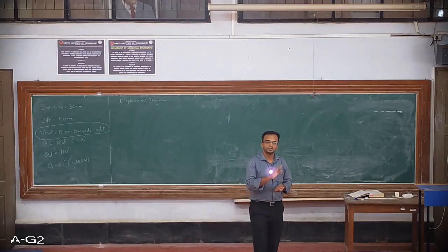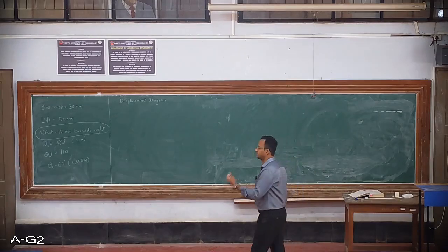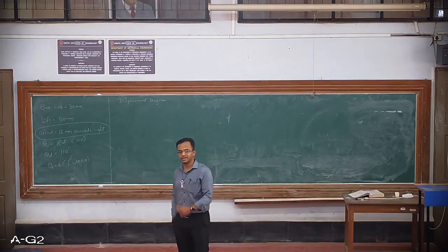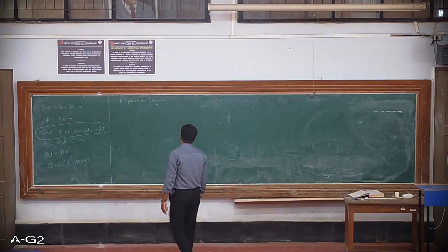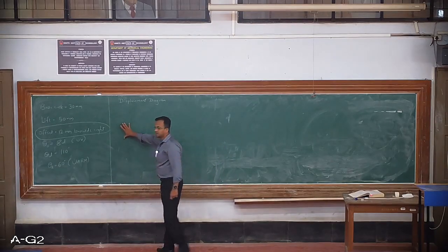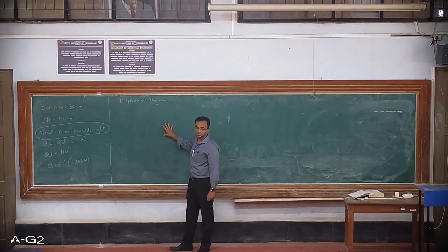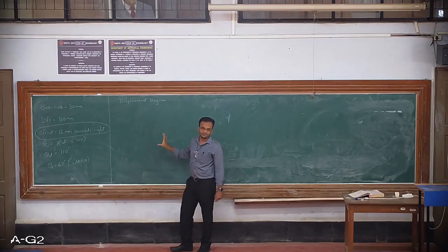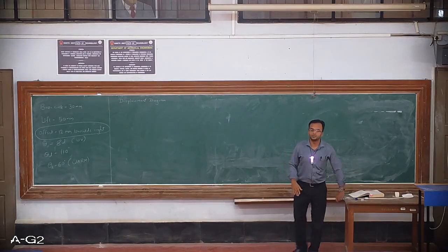That means you have to convert 360 degrees into some suitable length, that is either you can make it as 36 centimeters or 18 centimeters, or you can scale it down further also. And as suggested in the previous lecture, we require you to draw the displacement diagram in the landscape mode in your page so that it can have the better scaling and the error will be reduced here.